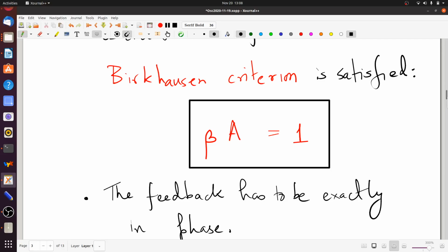And the answer to that is every electrical circuit has a lot of electrical activity going on inside it, even when there is no input signal. And this is because of the fact that electrons inside the components execute random motions. So there's always a lot of electrical noise, which is a tiny random signal of all possible frequencies floating around inside the circuit. So basically, it's this electrical noise which is going to provide the input to this circuit so that the oscillations can happen.